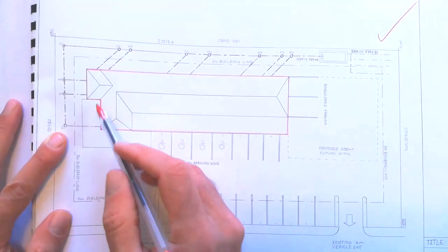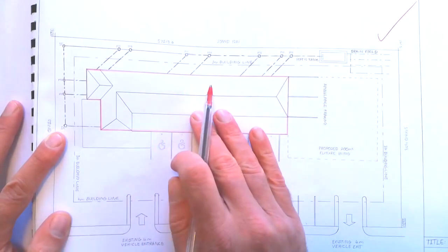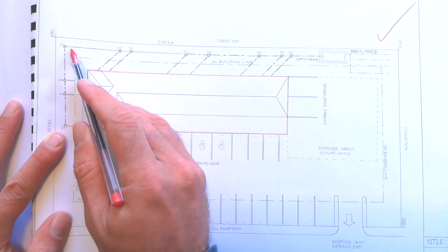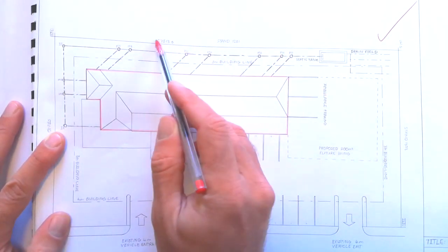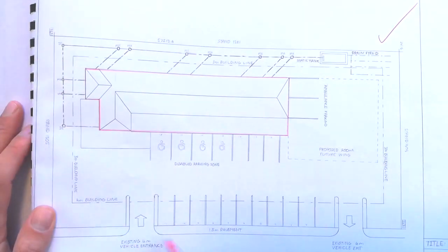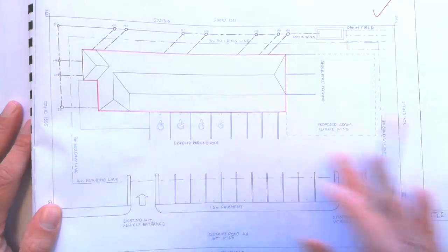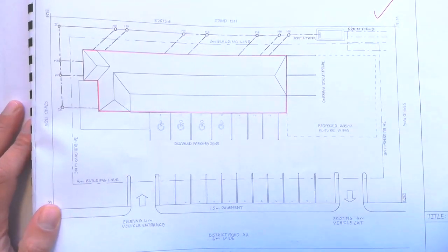Again, remember with the site plan, it's the basic outline that's required. You don't need any internal walls. Then you've got your sewer connection available, indicate your building lines, the corner heights, those kinds of things, the entrance, the road labeling, that all needs to be done correctly. Okay, that's an overview of the basic drawings that are a requirement.